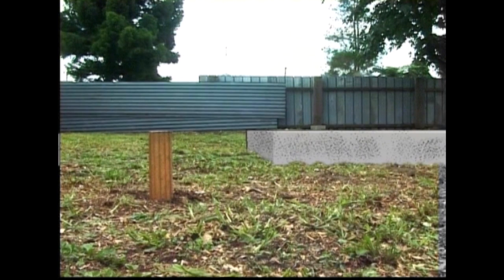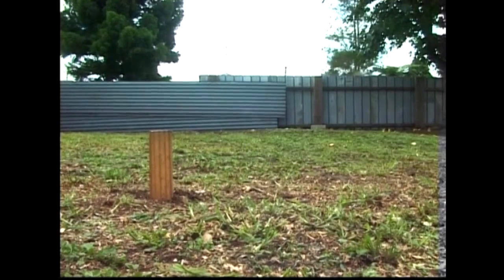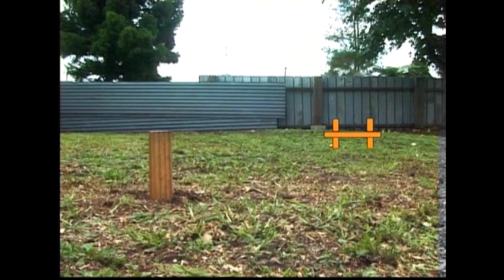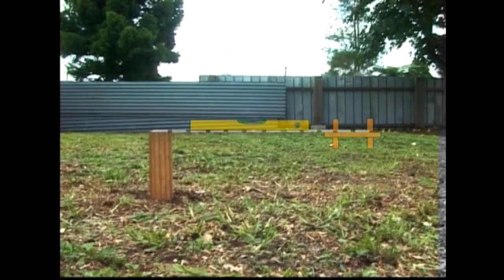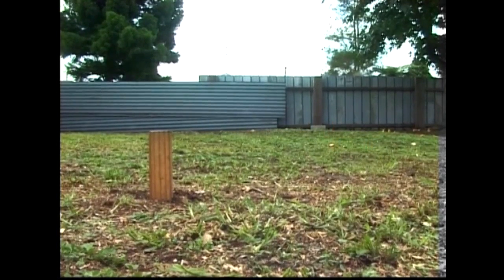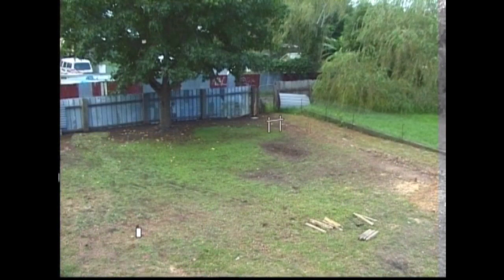Or in the case of a concrete slab, the reference mark is the top surface of the slab. Working from this established height, profiles can be erected with ledges levelled in the one horizontal plane. This initial height peg procedure is needed because the first profile setup will not necessarily be at the high point of the site.